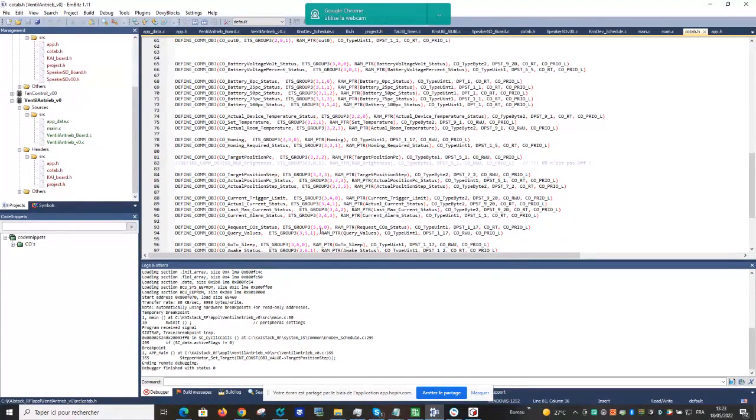In order to be able to debug and make tests, we will give them addresses. These addresses are the same as within ETS. They will be reprogrammed once the integrator uses ETS, but prior to that, we put some addresses at this place so we can use them. In this firmware, we have to put the addresses of the communication objects.